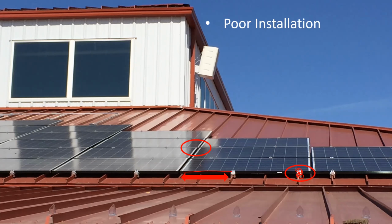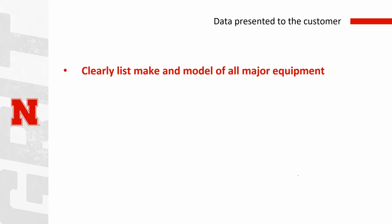The wind and snow loading is not going to be good for that. That's a real problem. This one's too close to the edge. That one's too close to the middle. But even if you don't know the installation guidelines, you know that that's ugly, right? You can go and look at these and decide what you think. But it really is important to have a good quality installation: straight lines, wires all tucked up nice, covered if they have to be, things like that.